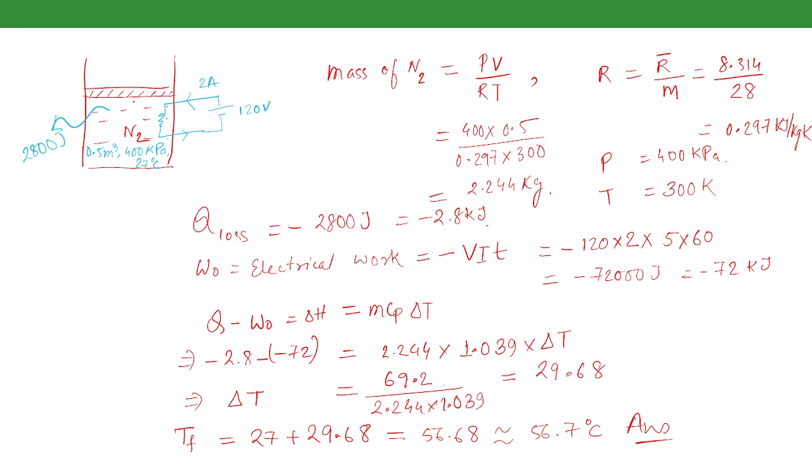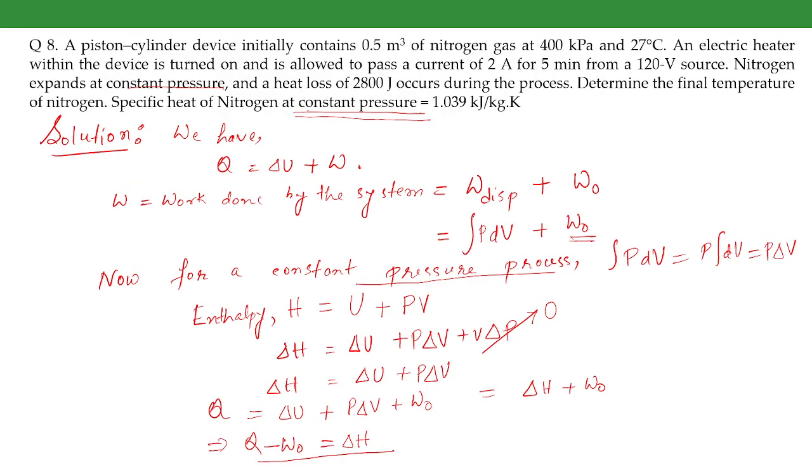It is the same thing in this case. Due to the temperature, there is an increase in pressure, which in a very small amount of time will increase the volume by a very small amount, resulting in an equivalent decrease in the pressure and keeping the pressure constant. That is why we are taking P delta V, and that is how we are taking it as quasi-static. So I ask if there is any doubt in this. Essentially, this expression, the integral of P delta V, can be written only for a quasi-static process.